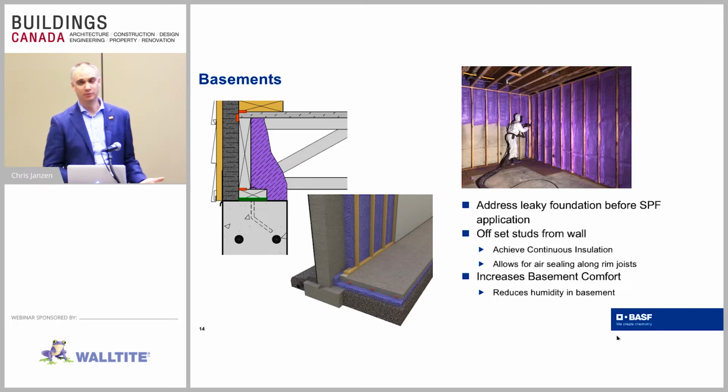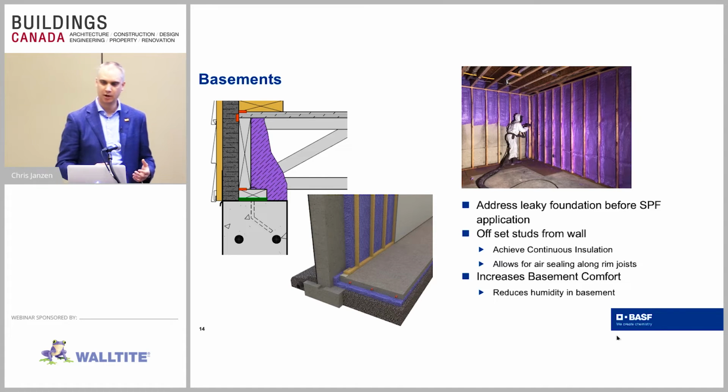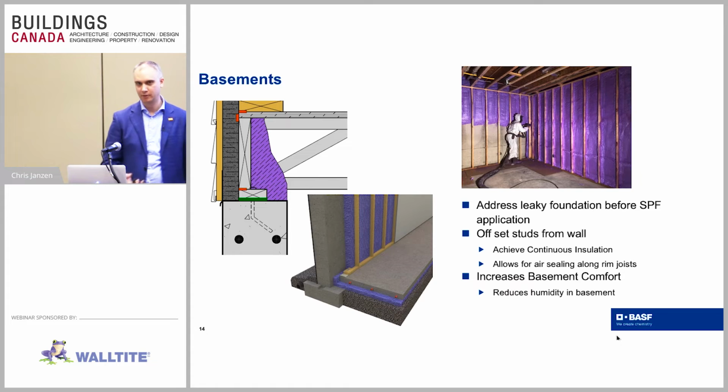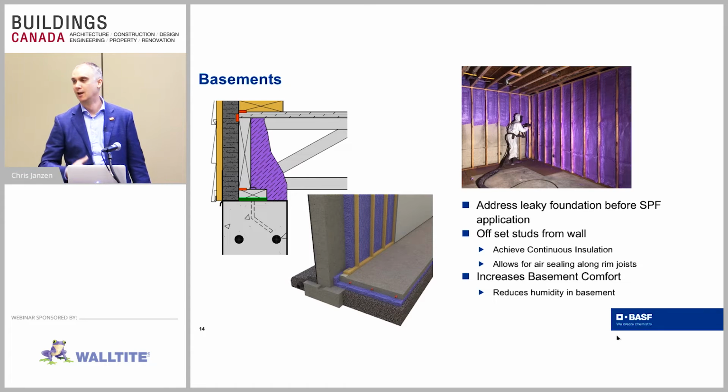One of the benefits of doing spray foam in the basement, other than just air sealing the rim joists, is that it gives the homeowners warm floors on the first floor above the basement. Also, because it's controlling the humidity level in the basement, you're not getting as much vapor drive coming through the walls. It gives more comfort down in that basement, and it gets rid of that humidity and that musty odor, that musty feeling you sometimes get in basements. If they're running a dehumidifier in the basement, it's not going to be running as much because you're controlling the humidity by using a closed-cell product like spray foam.